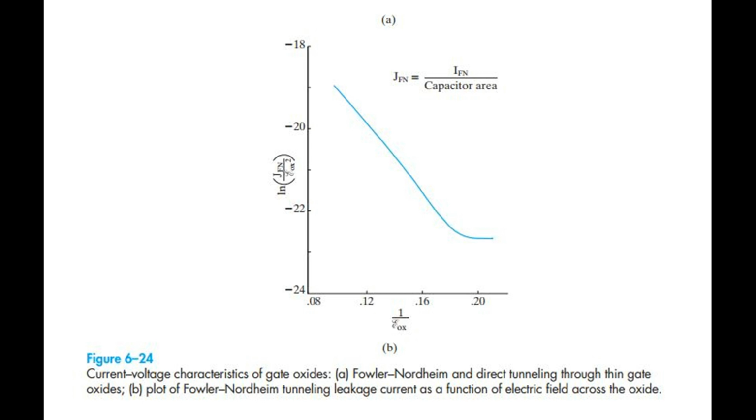Such tunneling currents are becoming a major problem in modern devices because the useful feature of high input impedance for most devices is degraded. It is necessary to increase the gate capacitance in successive generations of MOSFETs in order to increase the drain current, as discussed later in section 6.5.